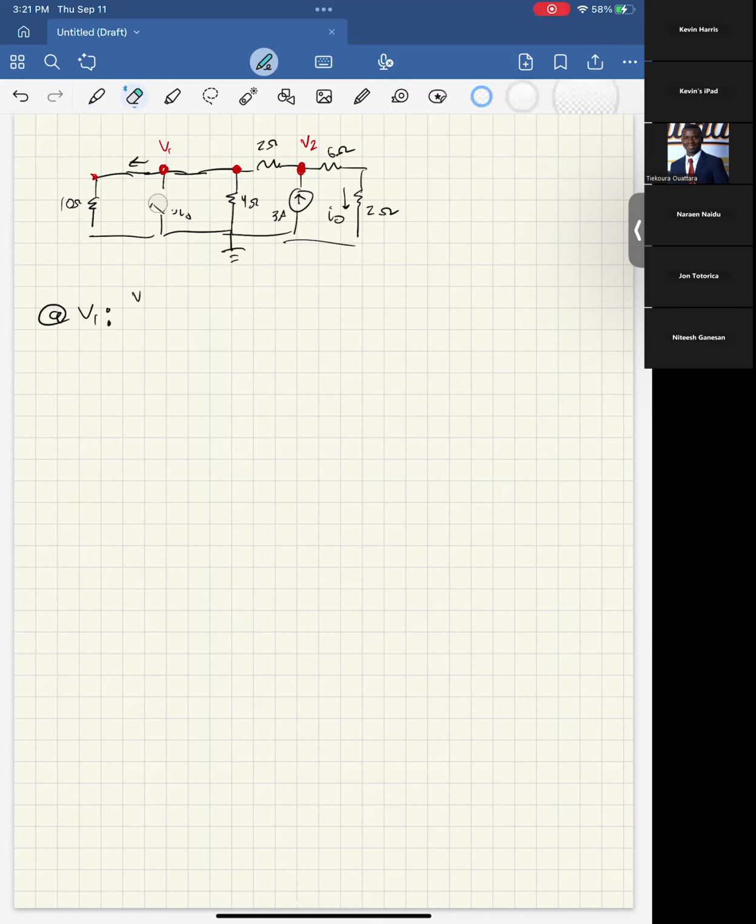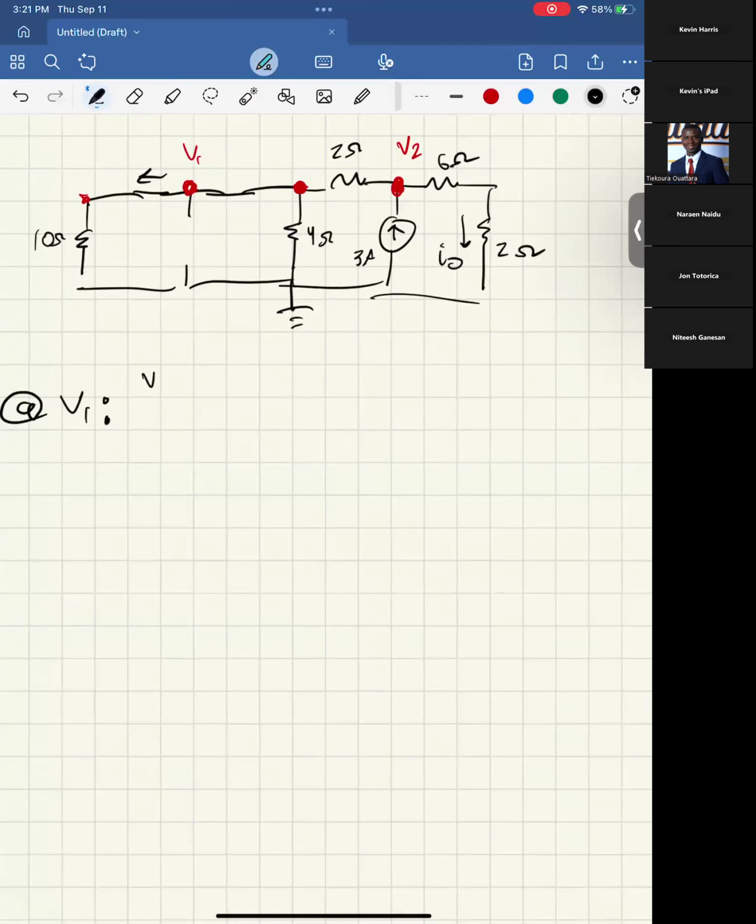Oh, actually, this is a bad question because that's already defined. Hold up. The reason this is bad is that since I put a voltage source here, that's explicitly telling you that V1 would be equal to 3 I naught. Hopefully that's clear for the same reasons I said before. Since this is a voltage source, it's telling you that between this point and this point, there is a voltage difference of that much. So pretend this wasn't a voltage source, because that kind of breaks my example. This is another resistor, and this is 4 ohms.